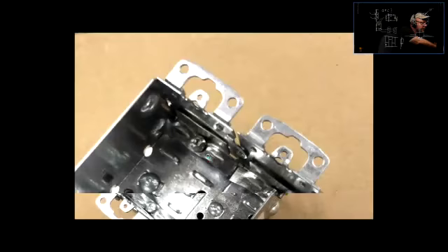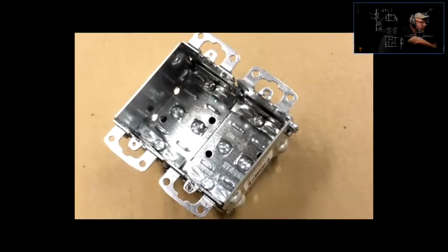Okay, here it is. I want you to see some of that. Not all, but see that this wall was removed from one box, and of course this wall was removed from the other box, and they are joined just like Lego blocks. Not all of them are doable in this way, but some of them are called gangable boxes, and you can make one solid double gang box out of two single ones.